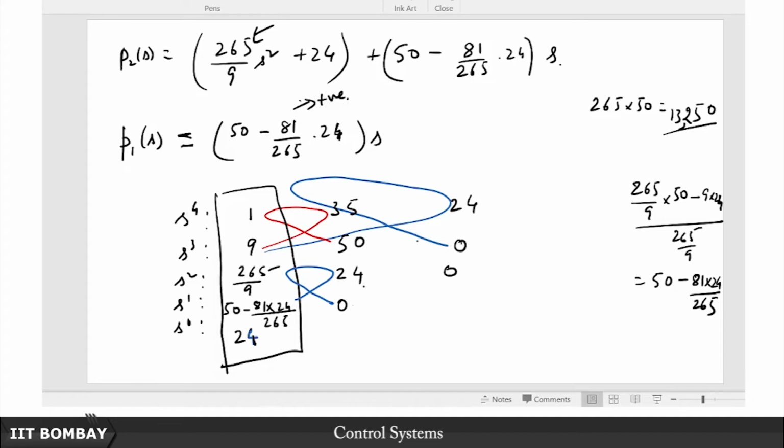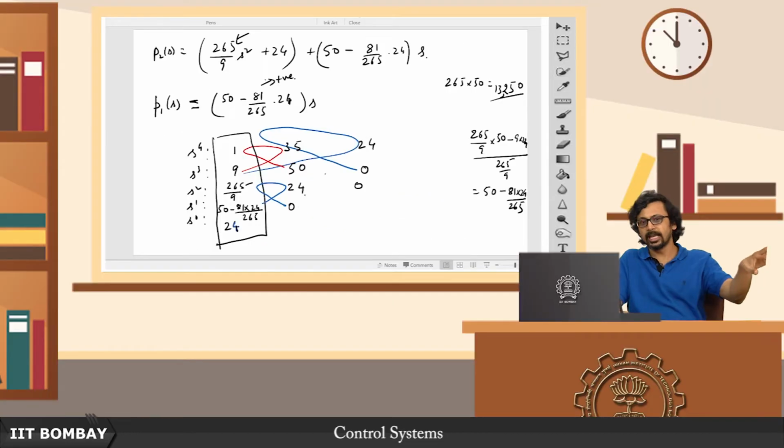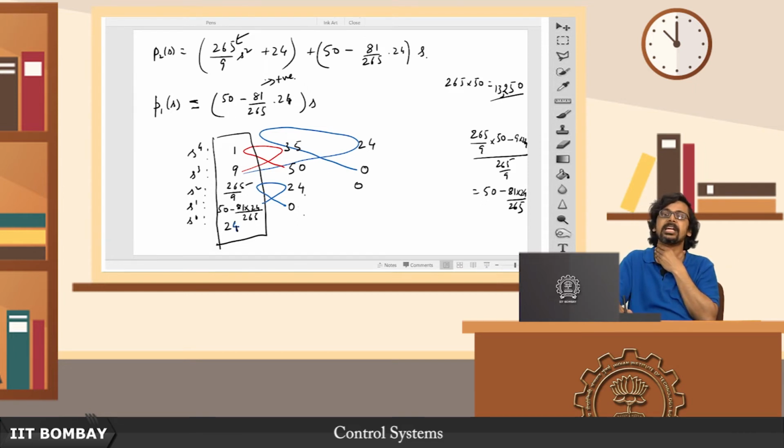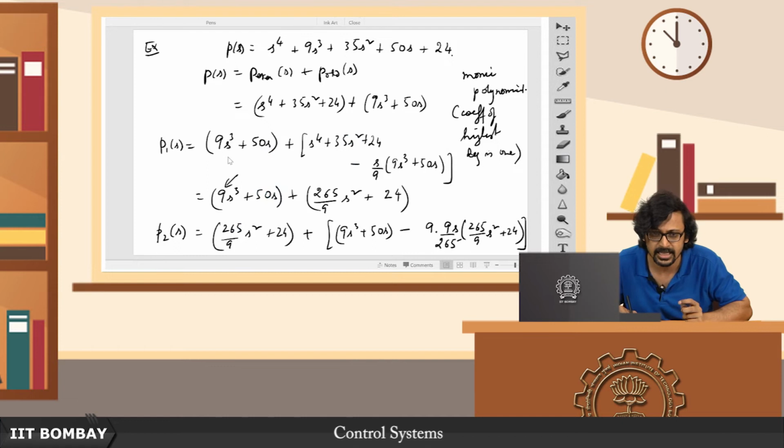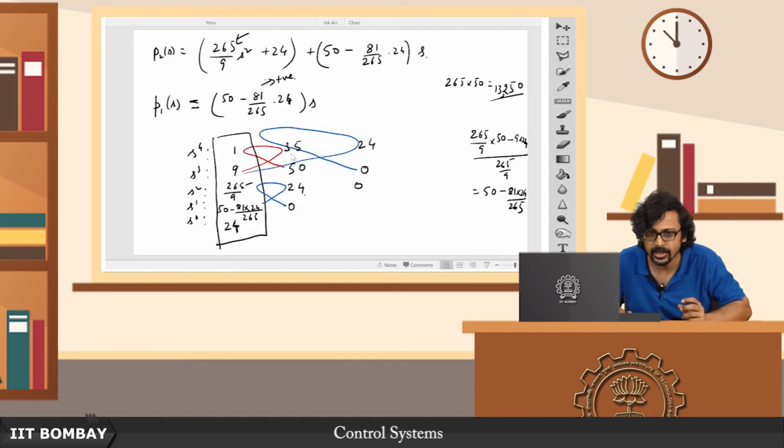In other words, if this Routh array has to correspond to a polynomial whose roots are all on the open LHP, then there cannot be any sign change in any entry of this Routh array, not just the first column. And by extension, of course, the first column is just a subset of all the entries, so it is also true for the first column as well, right? And the reason being, as I said, now you can see this clearly, at every stage these entries are nothing but coefficients of certain polynomials.